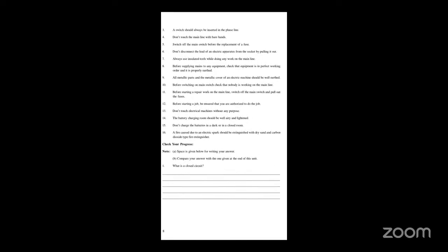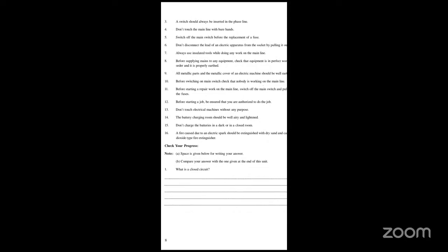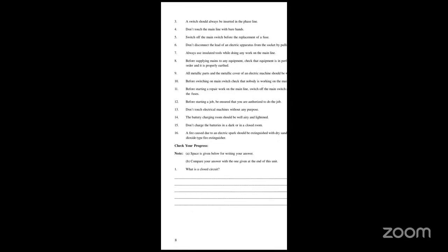Now, a switch should always be inserted in the phase line. What precautionary measures do we want to take? These points are required. First, a switch should always be inserted in the phase line. Next, don't touch the main line with bare hands. Switch off the main switch before the replacement of a fuse.